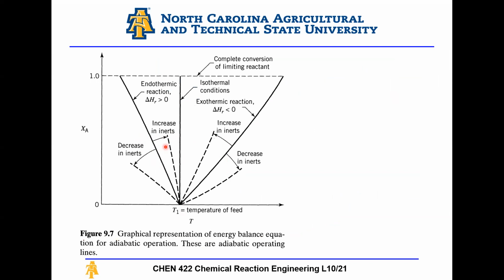So for example, if I have a gas phase reaction and I purge it with nitrogen, the nitrogen will eat up a lot of this heat, and this will prevent a huge temperature increase in the system. Or, the most common example, a Fischer-Tropsch reaction: I have CO and hydrogen, highly exothermic, so I run it in a reactor full of wax, and this wax eats up all this heat, so I don't have a large temperature jump throughout my reactor.